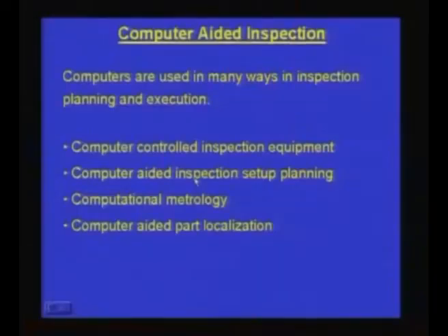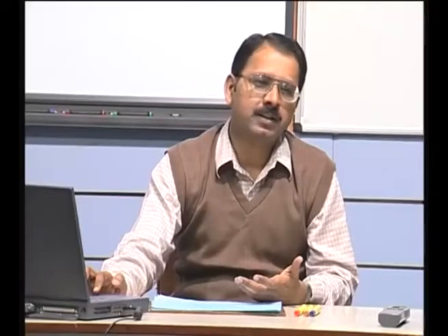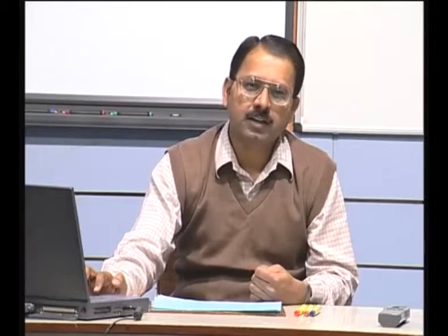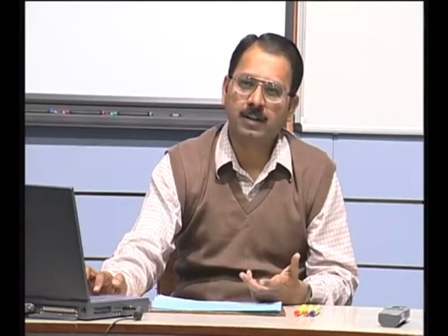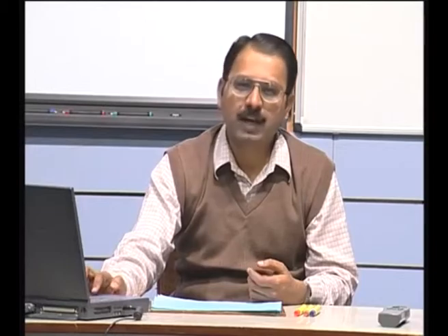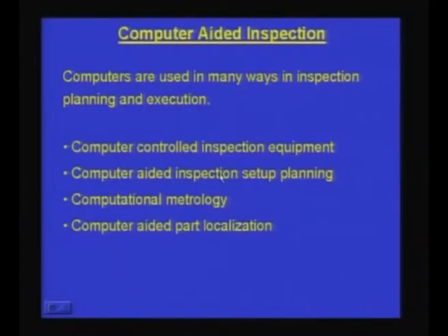or I may be looking at computer aided inspection setup planning. One of the important decisions in inspection is, if I have a component which has to be inspected for certain tolerances and other features, how to set up this particular component for the inspection process itself. Either it may be an in process inspection or it may be an inspection after the manufacturing. So, this planning can also be done using computers, and computers are used in metrology, in what you call computational metrology.